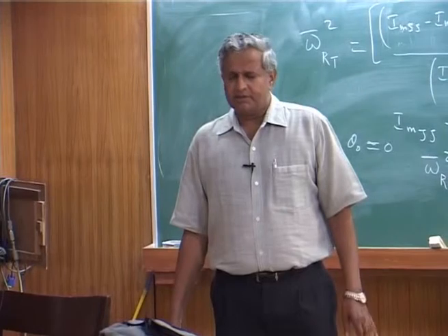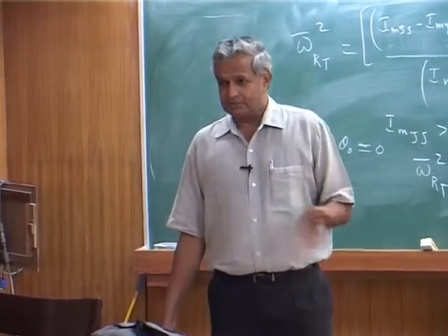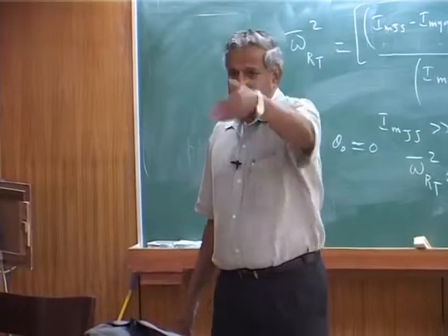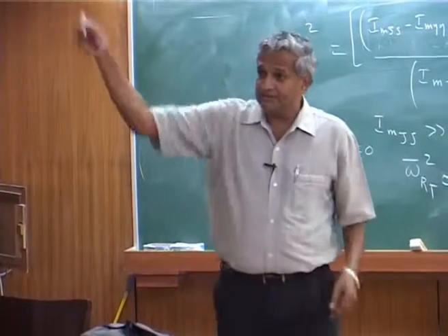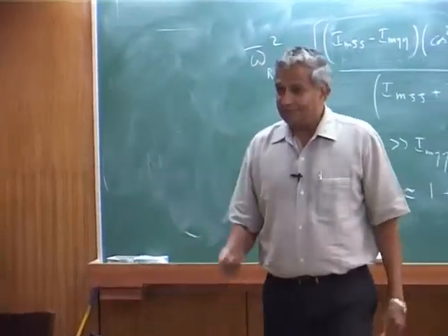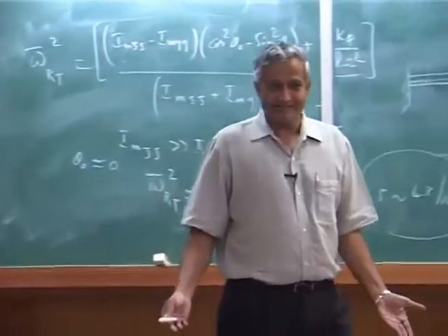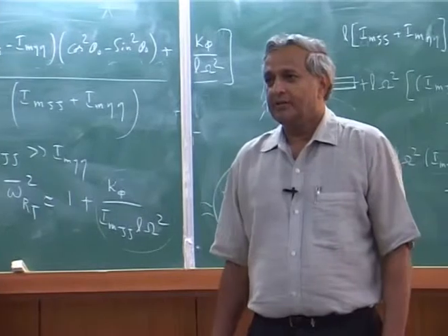Aerodynamic force. Between static wing and rotary wing, there are plenty of differences. First of all, the flow velocity is varying across the span. You will have a radial flow, and you have an inflow. Everything is there; flow is in all directions. Okay, inflow can be accounted for, but how to?